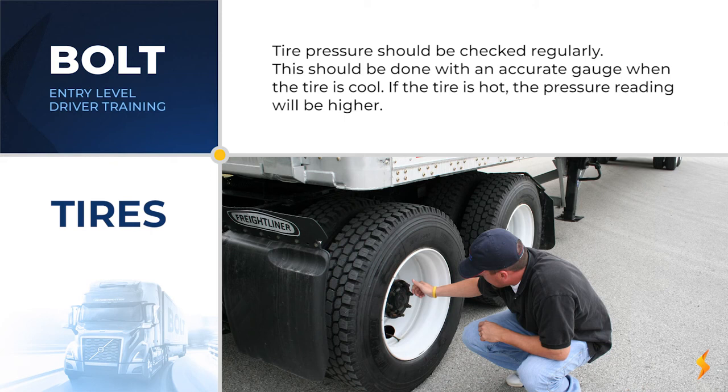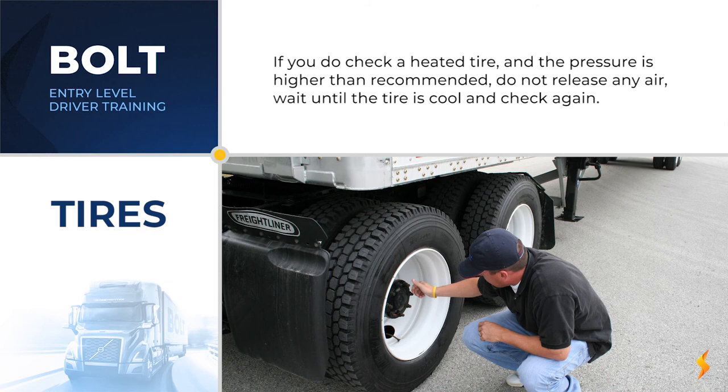This should be done with an accurate gauge when the tire is cool. If the tire is hot, the pressure reading will be higher. If you do check a heated tire and the pressure is higher than recommended, do not release any air. Wait until the tire is cool and check again.